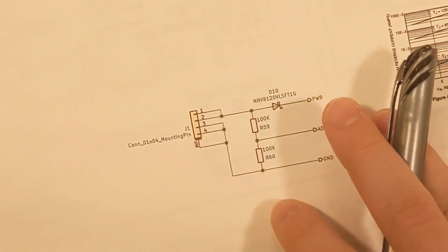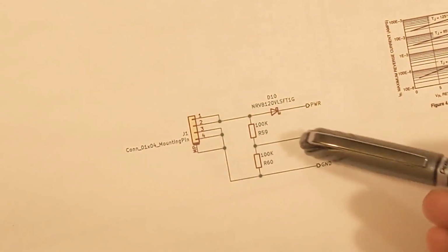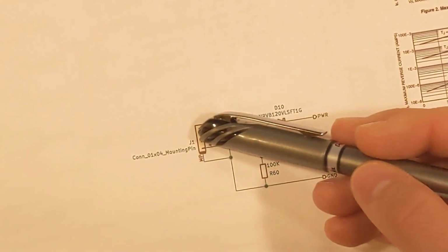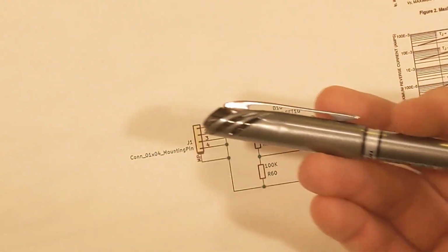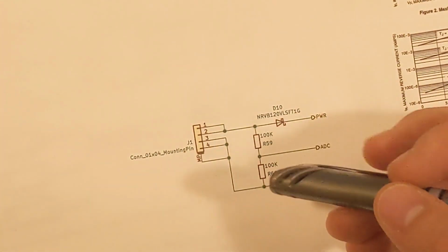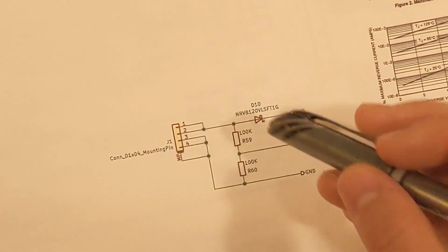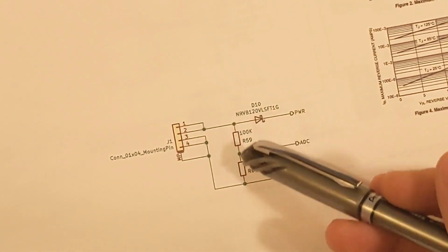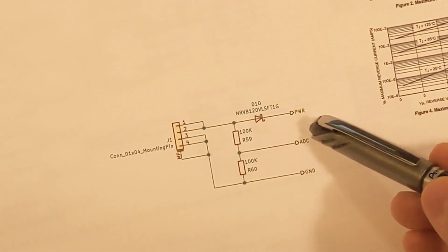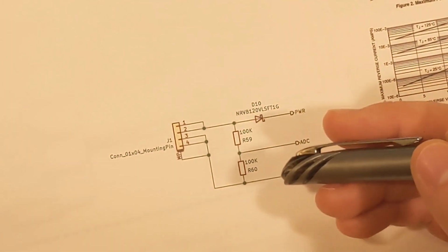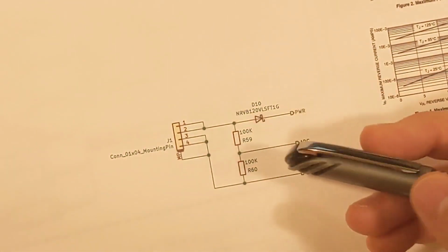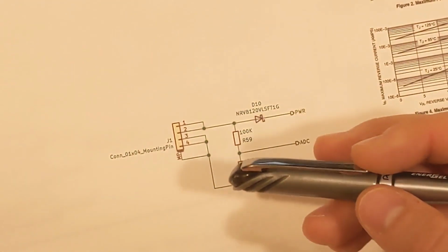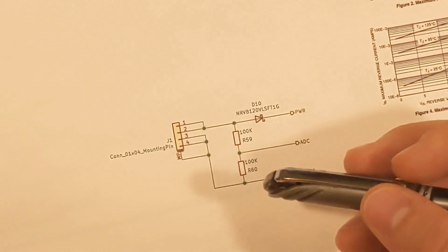So, looking at the solar cell connector, well, it's about as simple as this. It's just the connector itself, which at this point I've changed to just some through-hole mounting points to solder wires to, and then I incorporated the diode in here, and then there's a voltage divider here for the ADC input into the microprocessor, since the solar cells could output a high enough voltage where I need to divide the voltage in half to not hurt the microprocessor, or the PMIC specifically.